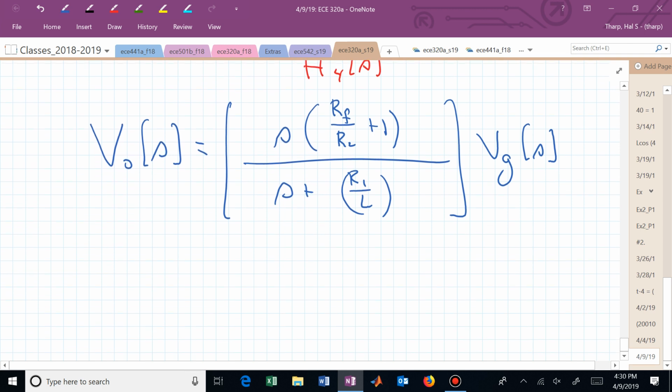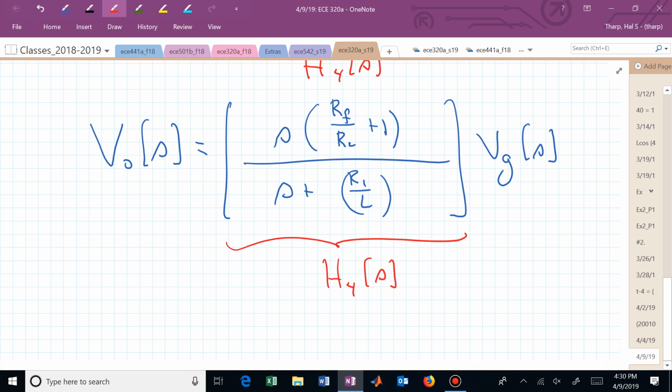And what do we have for a shape? What's this transfer function? This is now our h sub 4. At low frequencies, what does this give us? If I shake this really slow, or with a constant, what are we going to see at the output? 0, right? Because you have a 0 at DC. You have a 0 at the origin, at 0. So this has no gain at DC. At low frequency,